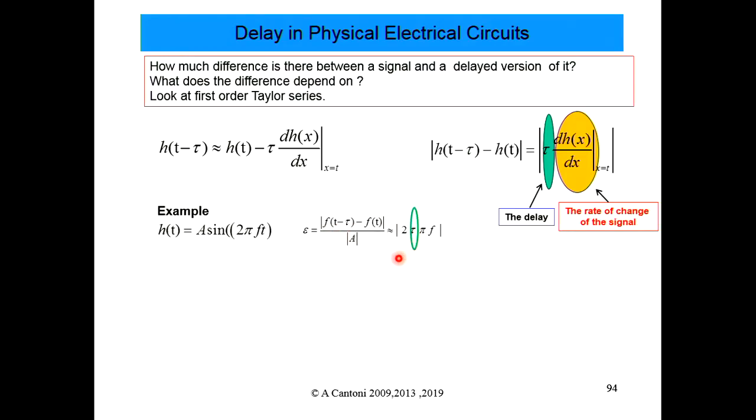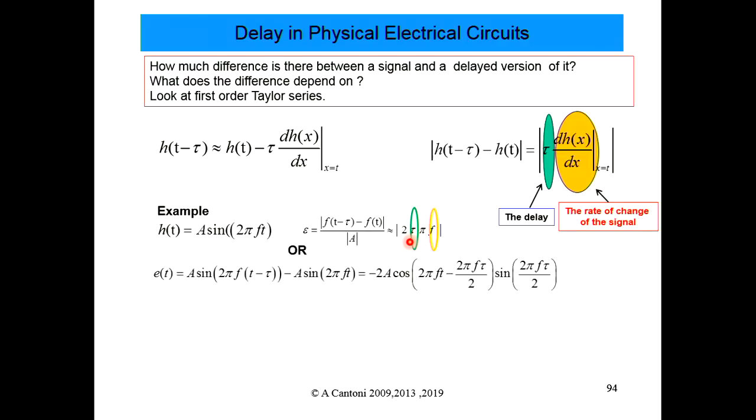And we can do that, and we can see that it basically involves tau and f, the product of tau and f. So we can go through and see that it is 2 pi f tau, right? And we want that, say, we want to make that smaller than some much smaller number. So we choose pi on 2.